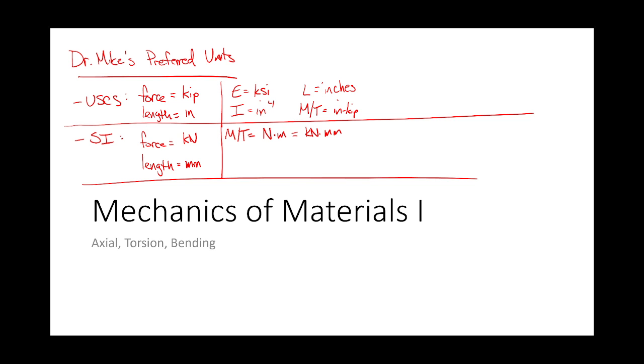And whenever you're dealing with stresses, which are going to be kilonewtons per millimeters squared, a Newton over a meter squared is a Pascal, right? So if you're dealing with kilonewtons and millimeters squared, we need to know what that equals in SI. In SI, kilonewtons over millimeters squared is gigapascals, because we have kilonewtons, 10 to the third, and we're dividing by 10 to the minus 3, but it's squared, so it's 10 to the third and 10 to the 6, so you get 10 to the 9th. That's where you get the giga.